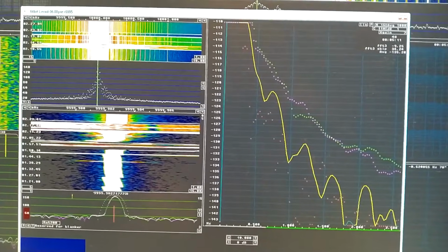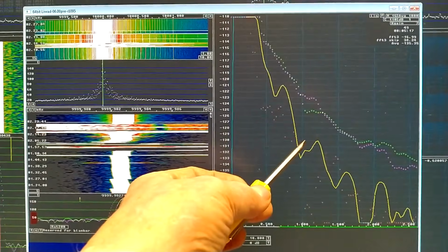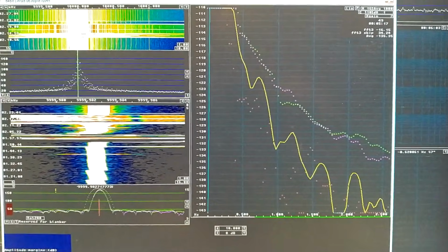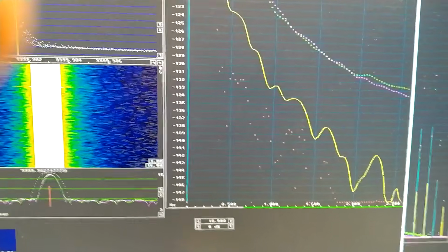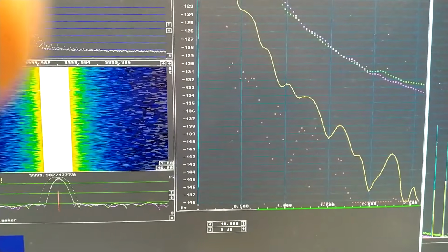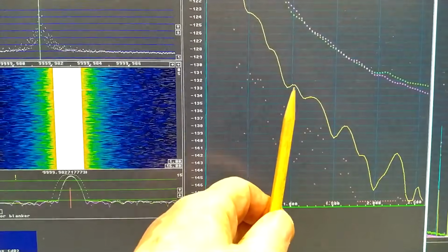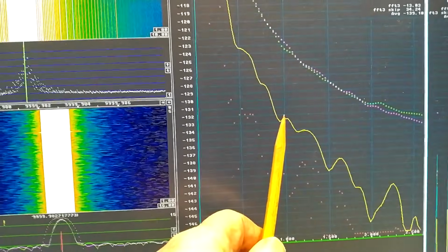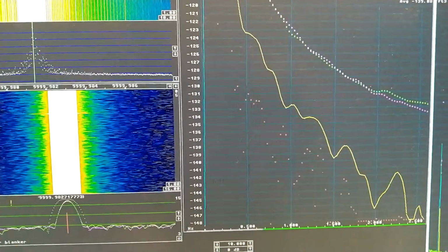This is only 5 minutes, and the average noise here is somewhere around minus 130. I wait for a while, and when I look here it looks normal also. The temperature cycling of the crystals seems to have solved the problem. Now at 1 Hz, it's here, a little bit better than minus 132 dBc per Hertz. And that's really good.